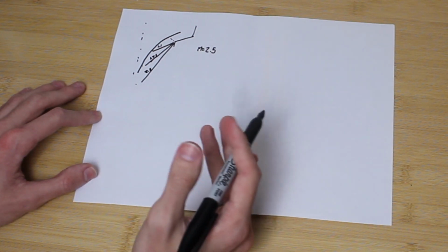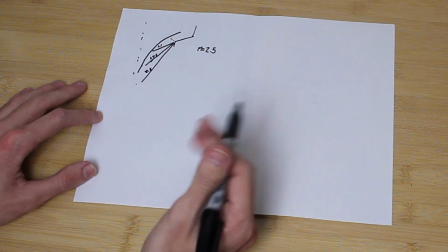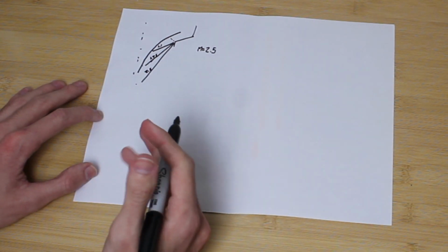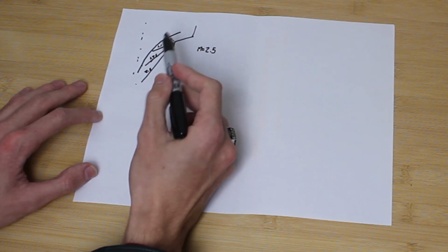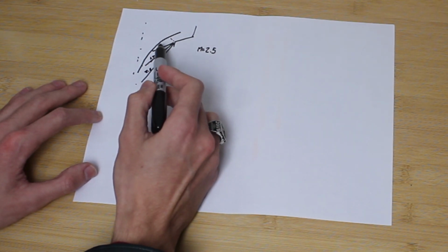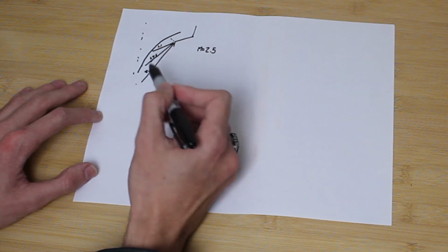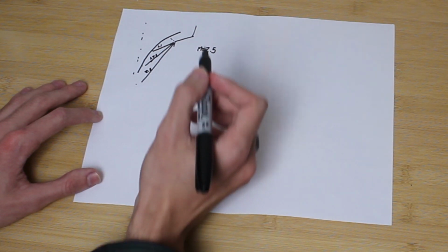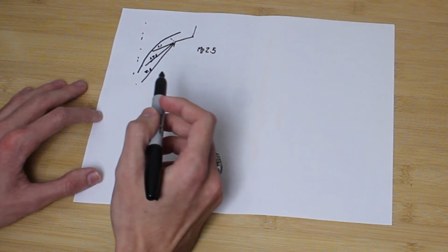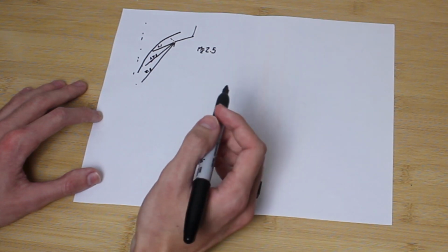So then you can imagine how, if we extrapolate this to designing a real aerospike, we would solve this, say, 100 times for a set of Mach numbers in between 1.0 and whatever our desired exit Mach number is. That would let us solve for the entire profile of our spike.